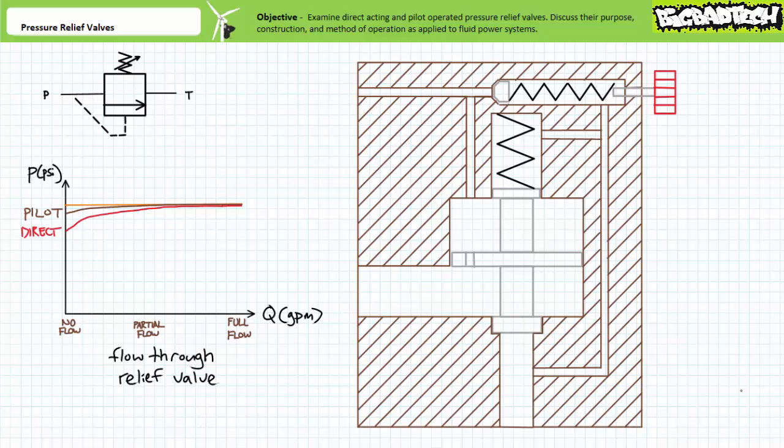This being said, a pilot-operated pressure relief valve overcomes the principal disadvantage of direct-acting pressure relief valves in that pressure override, the region between cracking and full open pressures, is considerably less, often on the order of only 25 to 50 psi. This means a system employing a pilot-operated pressure relief valve will notice considerably less diversion of fluid operating at regions near the pressure set point. A pilot-operated pressure relief valve therefore allows a more predictable response to a user-imposed pressure limit.